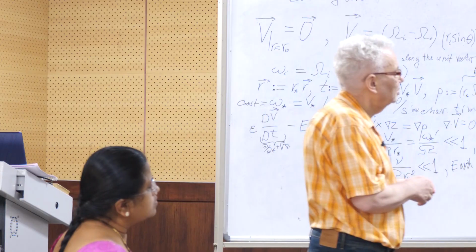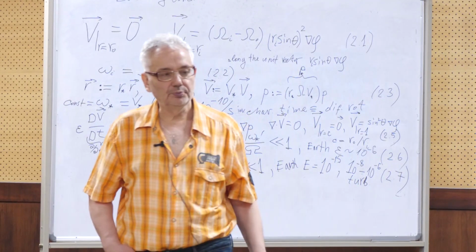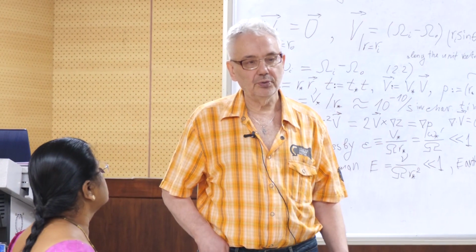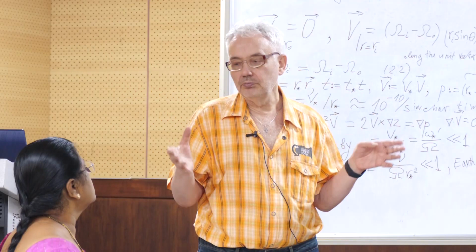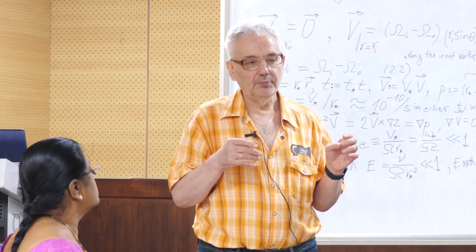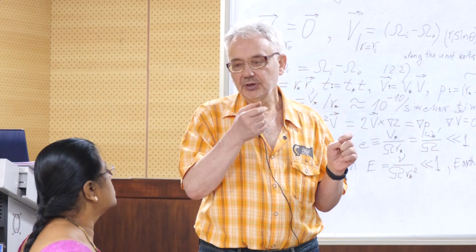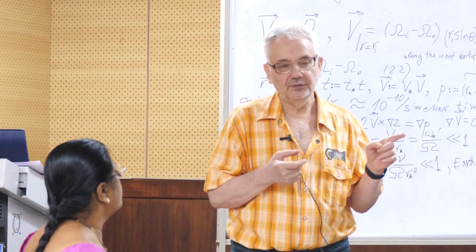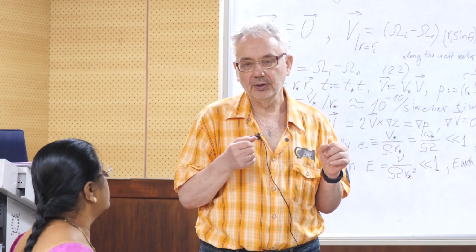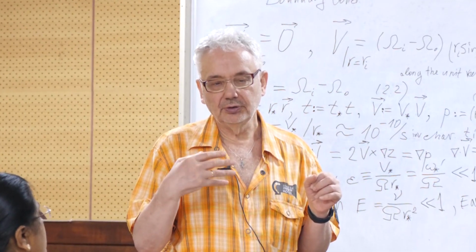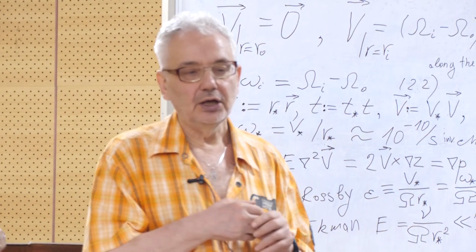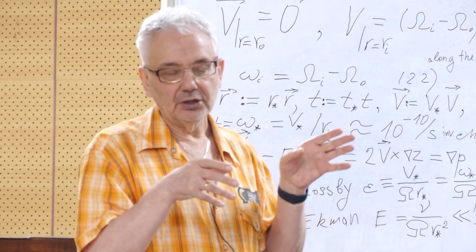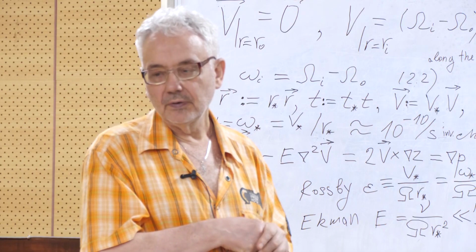So we're using the advantage that this Ekman term should be kept somehow. And so it's reduced the problem from the full bulk of the core to some boundary layer or shear layer. In this case, we have a very important boundary layer, the Ekman layer, and also some shear layer appears, first of all, on the tangent cylinder, because they are also very important.